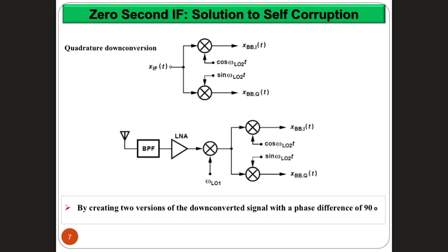And then based on that, if we look at the in-phase and the quadrature component and add them together after doing demodulation to 0 IF, the second stage, you will see that the resulting signal after you add those two together is going to be as if you have flipped the other one and added it.